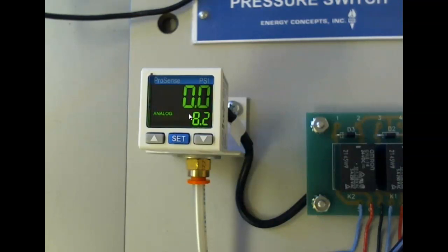And of course, it's programmable. What's neat about this one is it provides not only a digital output, it also supplies an analog output. With the digital output, we can set it up to measure a span for us, which means we can set it up to give us a low and high range, or we can set it up just to measure pressure. And it also can measure a vacuum. I don't remember how low it goes, but it measures vacuums or pressures. Are we okay?